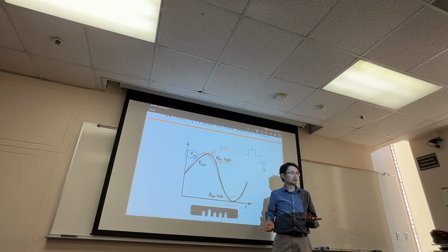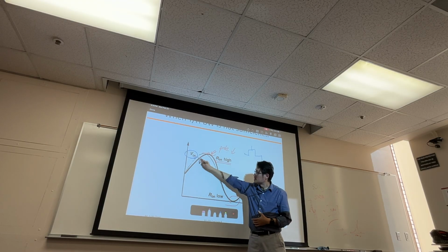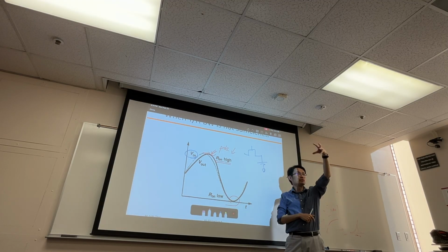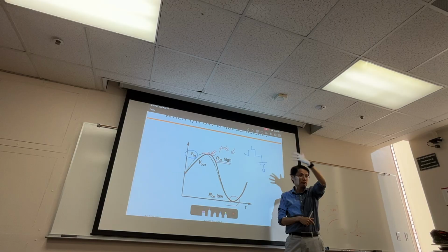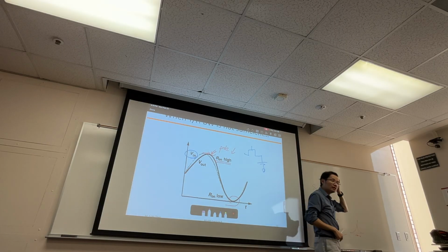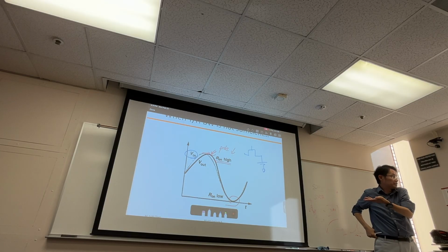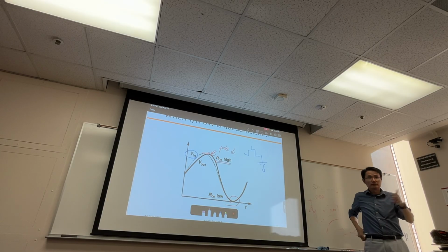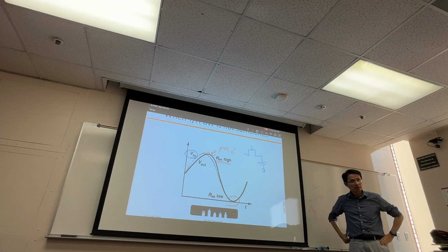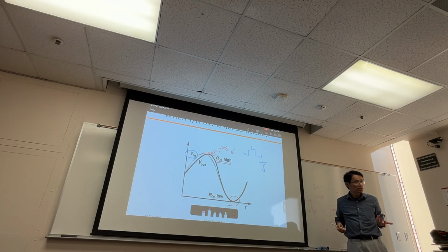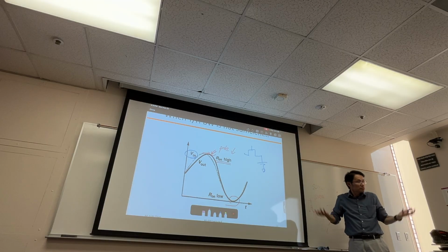Okay, so what kind of wave is this? Originally, it was a perfect sine wave. But then if I tell you that, by the way, the top one is going to delay a little bit more, and I do FFT on this, because at the end of the day you're going to do FFT, right, assuming you do proper windowing and all that, what does the spectrum look like? Does the noise floor go up, or distortion, so it means that you have harmonics? Which one is it? Or both?